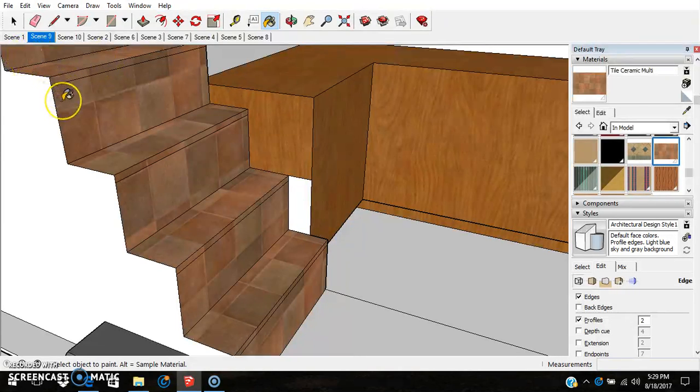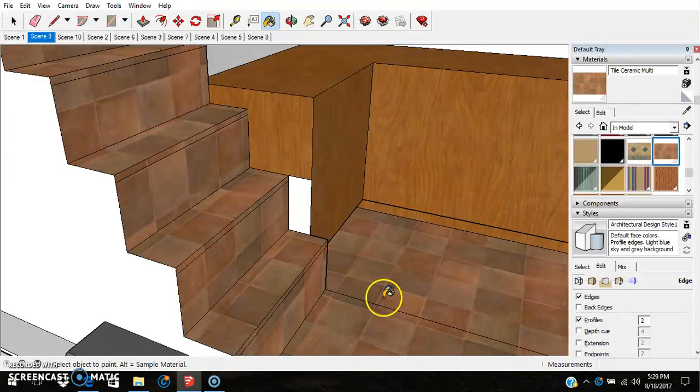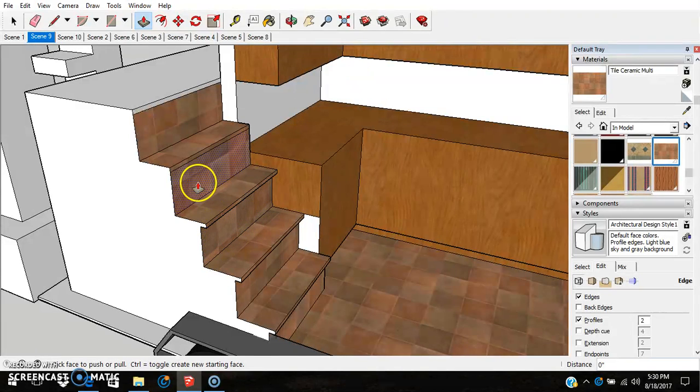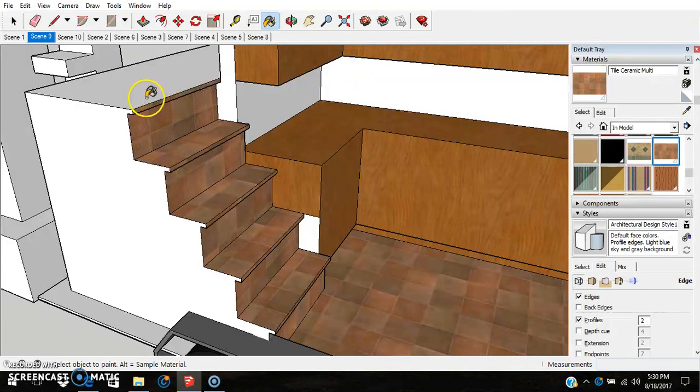I probably should have even added the texture before I added that bull nose to it. Okay, back off, and now we can repeat. We'll push these in 1.5 inches. Just punch that in, and we're using the push-pull tool P, and we'll go ahead and just add that texture to the bedroom floor. All right, well, making some progress here.